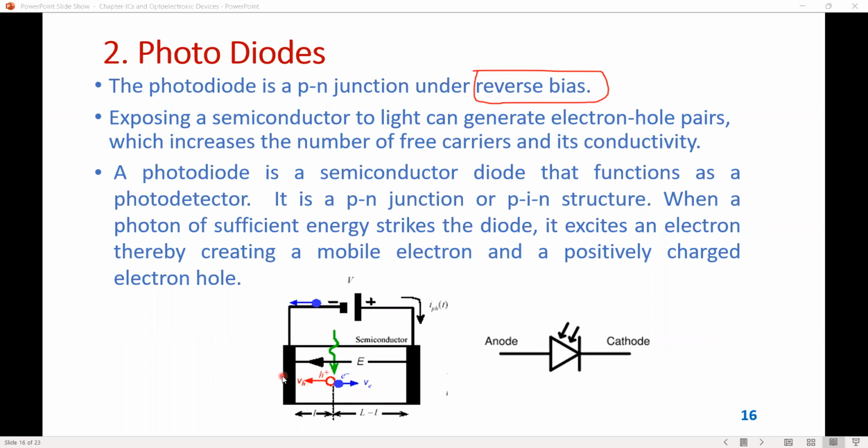You look here. So first, what is a photodiode? It is a diode which works in a reverse bias. So we connect it in the reverse bias. Because of it, what happens? The depletion layer becomes wide. We discussed it. So this region we expose to the light. Whenever light falls on this depletion layer, you can see this green photon strike on it, so it releases its energy. When one photon strikes the semiconductor material, it gives its energy to the electrons there, which causes electrons to move. So when electrons move, it generates electron and hole pairs.